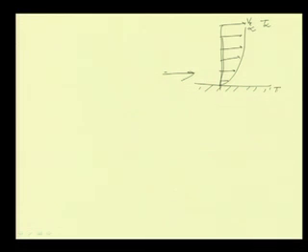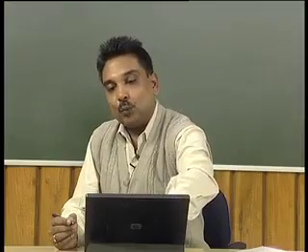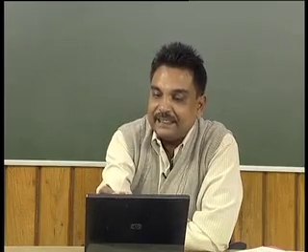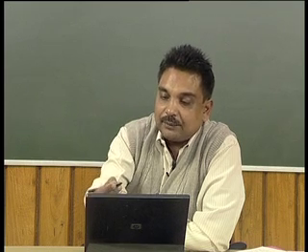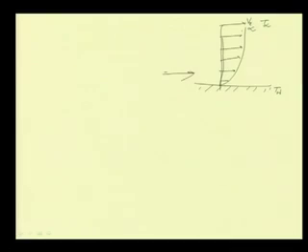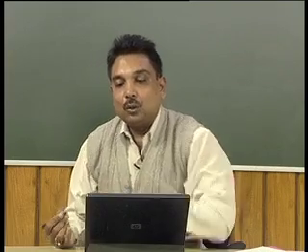Here it is T wall, the wall temperature, and the temperature T infinity is the free stream temperature. What is this free stream? Free stream condition is the condition when the effect of the wall is not experienced by the fluid element. That means the velocity of the fluid element is not disturbed by the opposing shear force offered by the wall or the consecutive layers, and the temperature also is not disturbed.